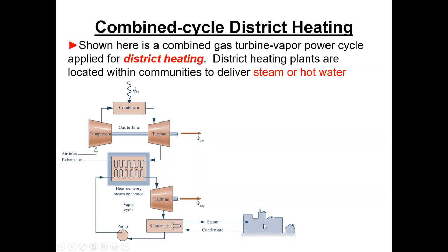But that's still running a condenser on the Rankine cycle. If you're set up like this, where you can take that heat out of the condenser and use it for something productive, your efficiency is going to go up another 10 or 15%. So if you were 60, this could be 70, 75% efficient.